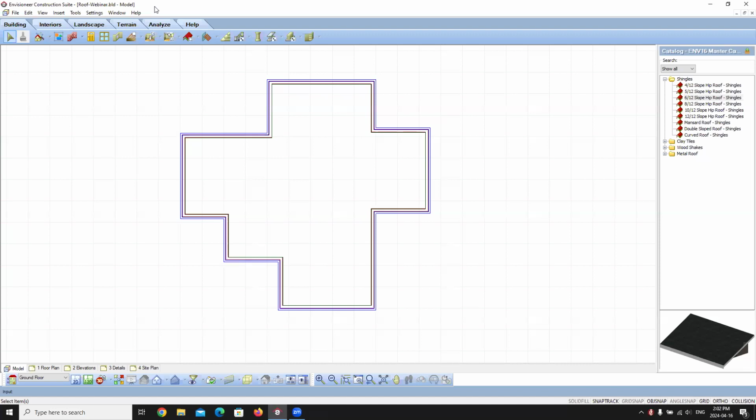So let's do a roof by picking points option. I want to show you how that would work, and then we're going to do a roof again, but we're going to use the roof by perimeter option. So let's say in our example that we have open on my screen, I want to add in a roof, and it's going to follow the basic shape of the design, but I want it to extend out in certain areas. So what I would do is I would go up, select my roofs option, and select roof by picking points.